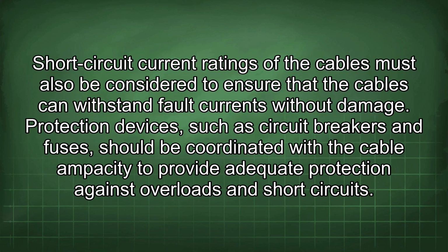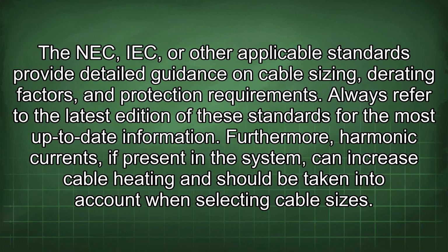Short-circuit current ratings of the cables must also be considered to ensure that the cables can withstand fault currents without damage. Protection devices, such as circuit breakers and fuses, should be coordinated with the cable ampacity to provide adequate protection against overloads and short circuits. The NEC, IEC, or other applicable standards provide detailed guidance on cable sizing, derating factors, and protection requirements. Always refer to the latest edition of these standards for the most up-to-date information.